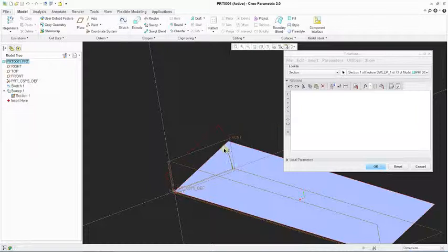I'm going to select SD6 equal to, and add the function trajpar. You can type it in or browse for it. Trajpar times 360 means it has to rotate 360, and I need to say the number of times, let's say somewhere around 10 times.